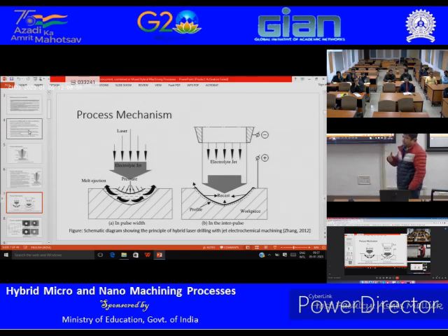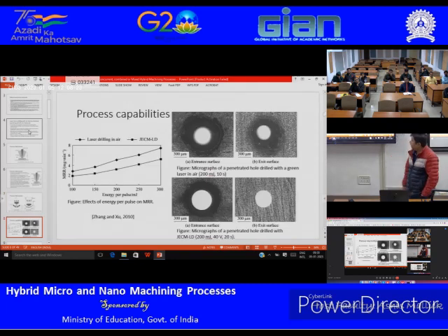So in order to maintain accuracy, you really need to know exactly what is happening, for which pulse energy you are selecting, and for that specific pulse energy, how much is the recast layer formation, right? And then you come up with the electrochemical jet nozzle diameter.